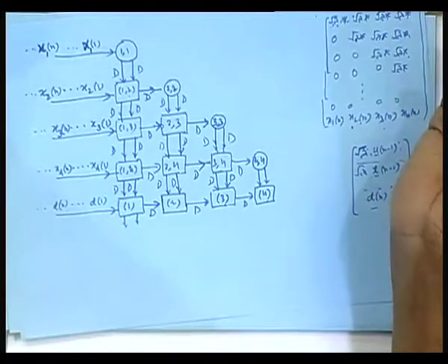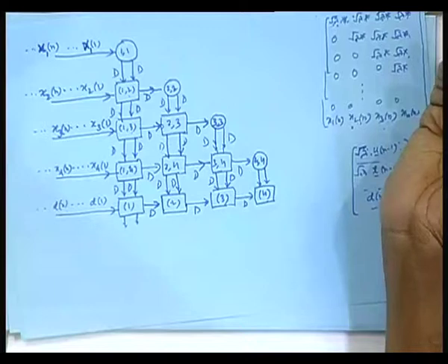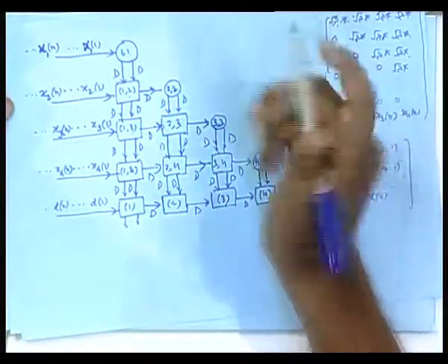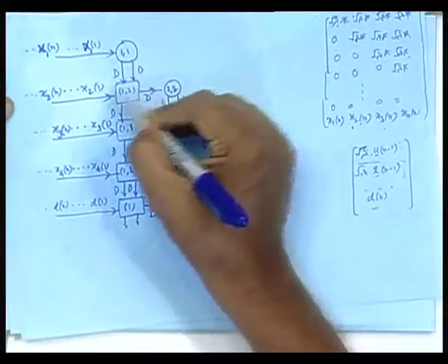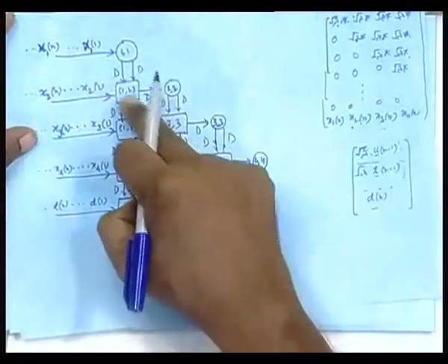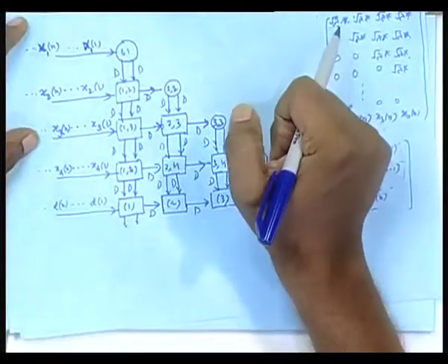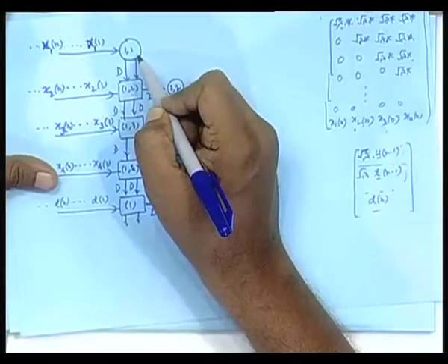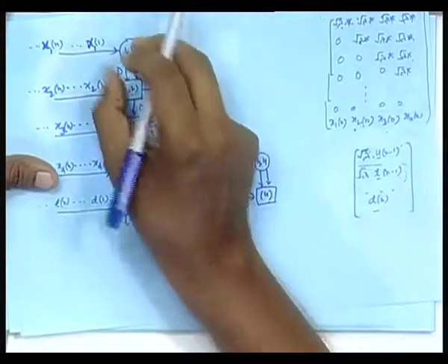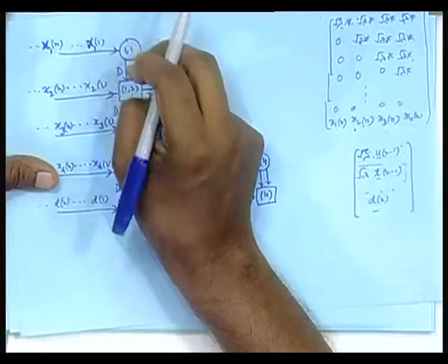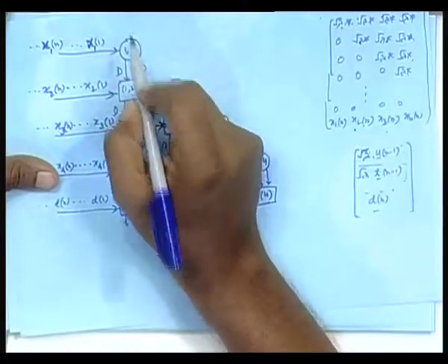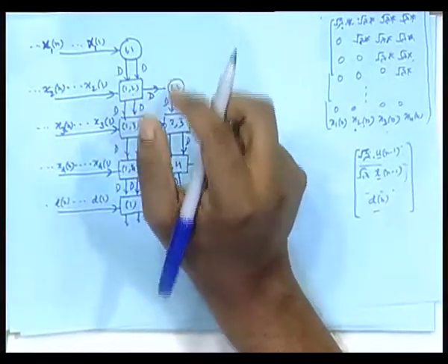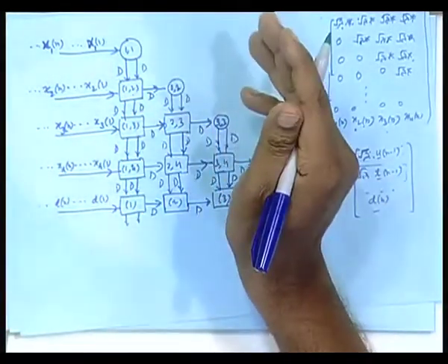So, that means my clock will be governed by what? Whichever of these processors takes maximum time, because all processors are pipelined. These latches are there between every two processors. Apparently this processor takes more time because of the square root computation, multiplication, all that. So, if it takes tau second or tau millisecond or microsecond or whatever, that will be the determining factor in my clock. My clock period just has to be tau at the minimum or it can be greater than tau, that is all.